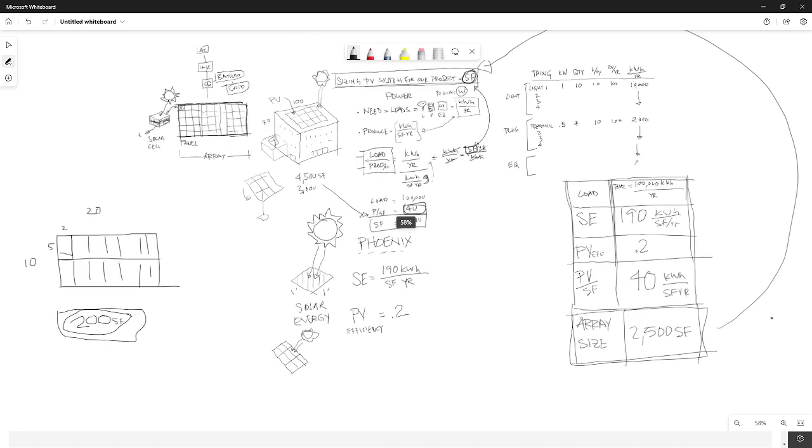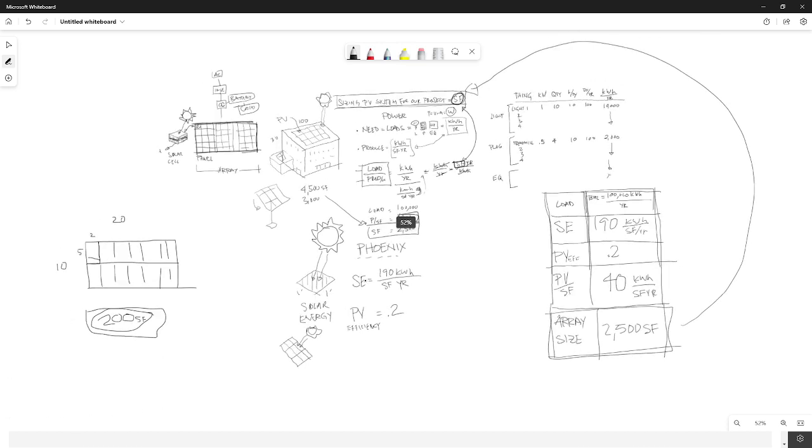And what this allows us to do is to use something like Climate Studio in schematic design to quickly calculate what we think would be an amount of PV solar electric we could collect on our site. And by the way, as you learn more about Climate Studio and how it works with Rhino, we can use Grasshopper, and there are things coming from the people who are doing Climate Studio, or we can make them ourselves, to calculate this for us. We could create parametric objects in Grasshopper that allow us to easily adjust the size of the system and see how much we're going to produce. So I'm arguing again that if you're interested in these things and want to be a little more technical in your architectural approach, keep your eye on Climate Studio. Keep trying to use it because it's very helpful in going to the next level.